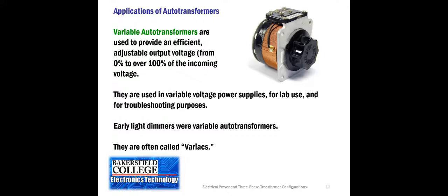And some autotransformers can even be connected so that you can get more than 100% of the incoming voltage. When they wanted to make dimmers in theaters and auditoriums and stages where we had concert lighting, before we had a lot of solid state devices, the transistors, the SCRs, the triacs, those things, this was the way they dimmed the lights in those theaters, was with an autotransformer.